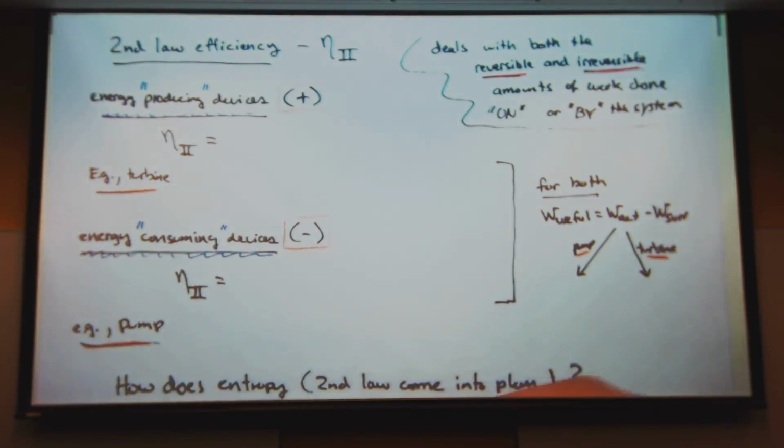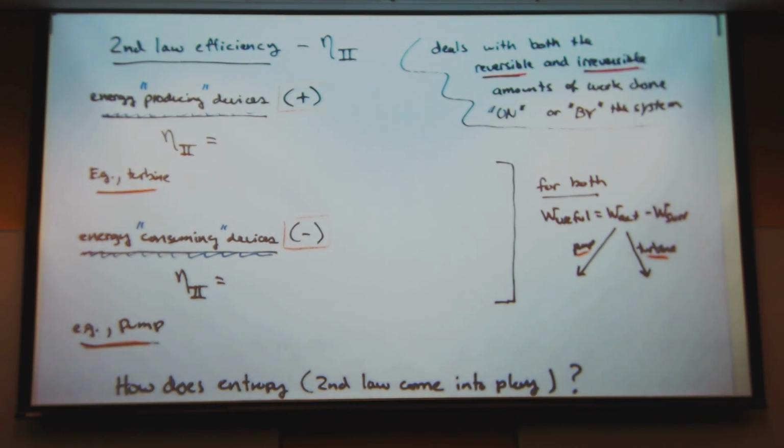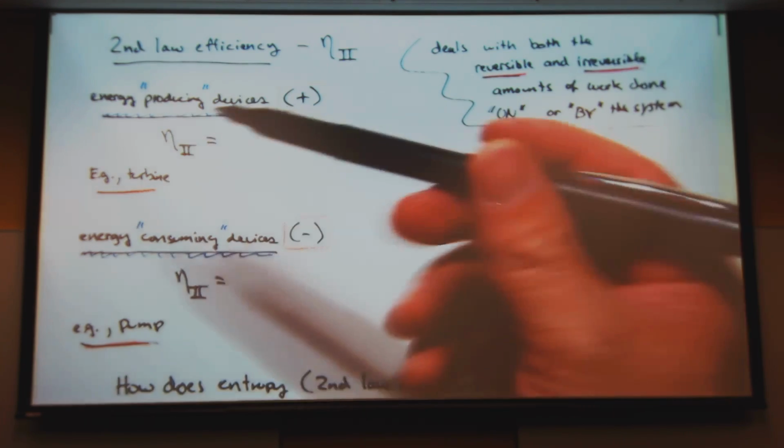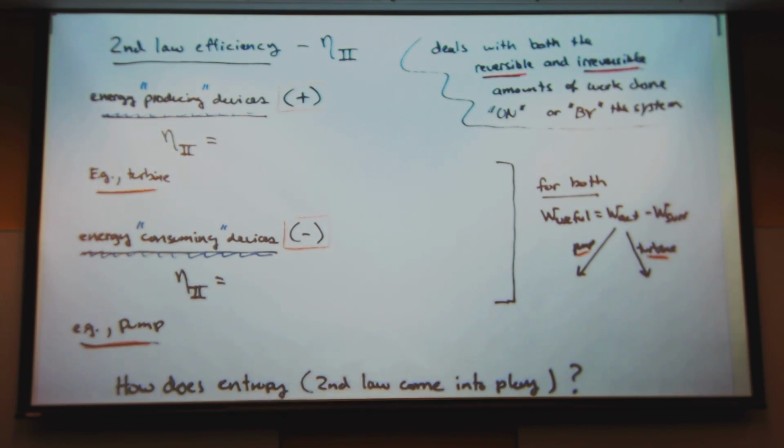And so for the second law of efficiency, I'm going to write down a bunch of equations. Really, you're not going to apply these until after, for like a month from now. But I'm introducing the idea of the second law of efficiency. So if I ask you, if the Q loss in this process went to 0, would the true efficiency be 100%? You'd be able to say no, but the first law of efficiency would say yes.